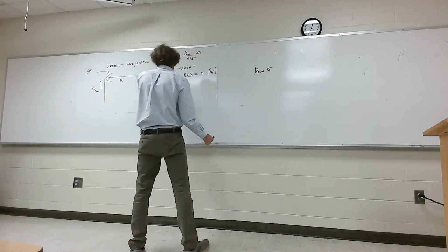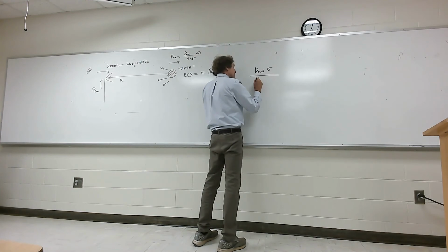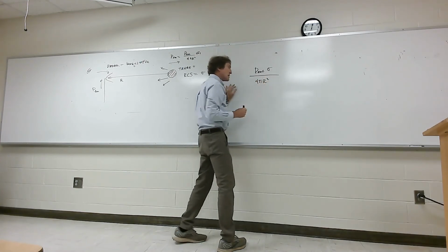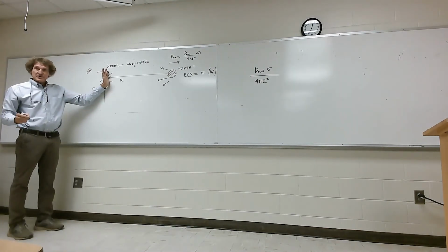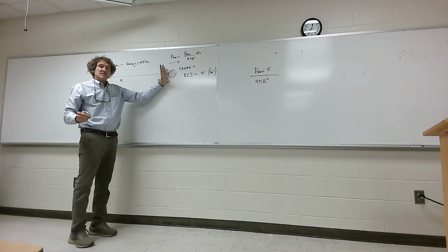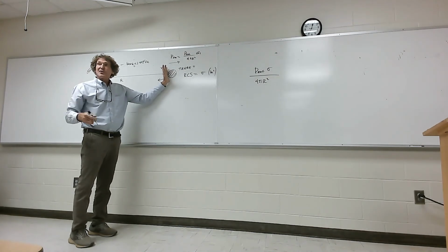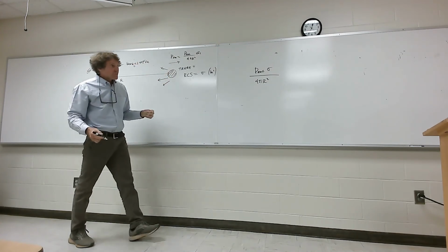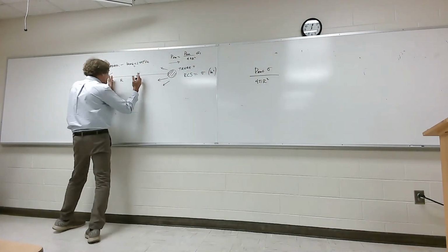Now, as it re-radiates, it falls off as 4 pi r squared as well. So this falls off as 4 pi r squared. And now that power density is what's back here. Do you follow the progression of this? I launch a wave, I have a certain total transmitted power, now I get the power density on this target. That power density hits the target. You might say the target catches a certain amount of it and re-radiates that power. All that re-radiated power falls off as 1 over 4 pi r squared. Now that power density is coming back here.